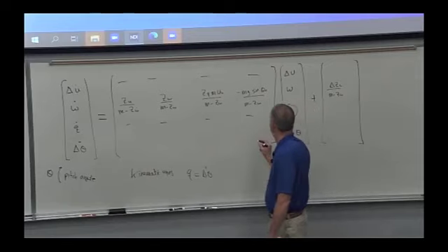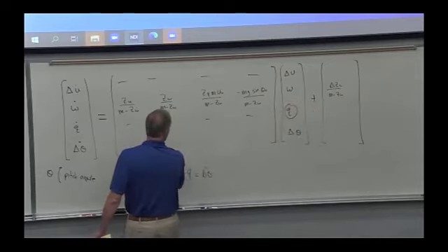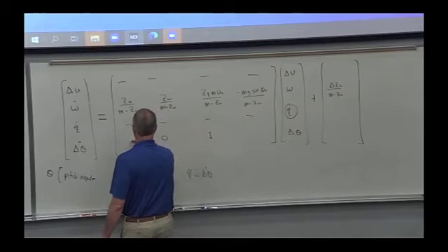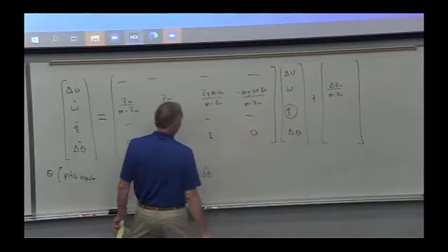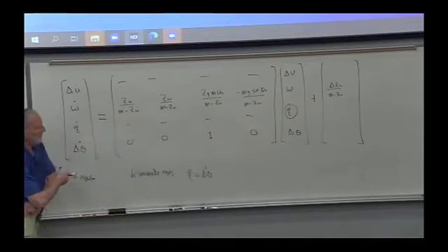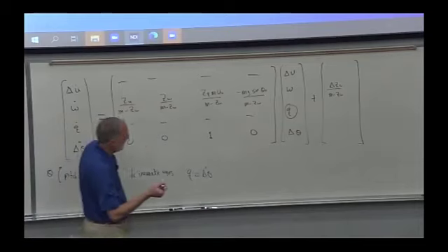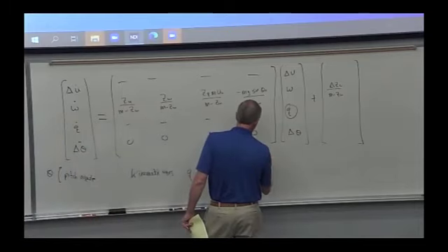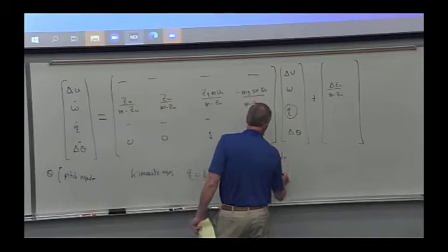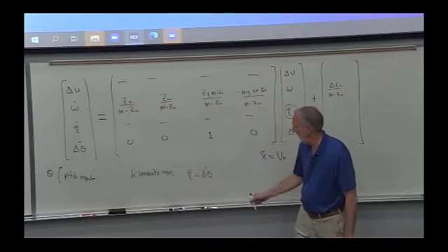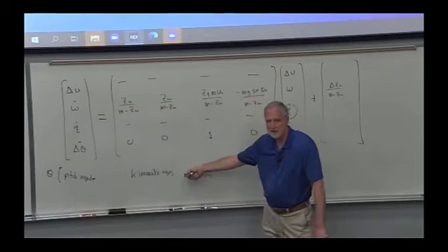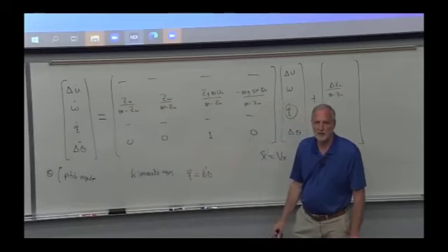And so that's easy to fill in, is that delta theta dot is q. And that's exactly like what we did where we said, well, we call x dot the velocity in the x direction. Here we're saying theta dot is the pitch rate. We just call it that.